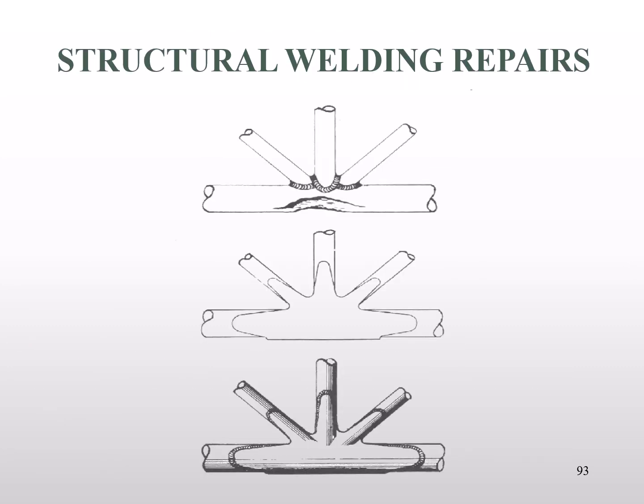Quite a few FAA questions may pop up asking you how to deal with different types of damage doing welded repairs. Well, one of the most complex types of welded repairs is when we get a dent or damage where there is a cluster of tubes coming together. Based on this illustration, you can see we've got 4 different tubes that are all coming together in one spot, and we have damage. Most tube repairs are done by cutting out the damaged tubing.